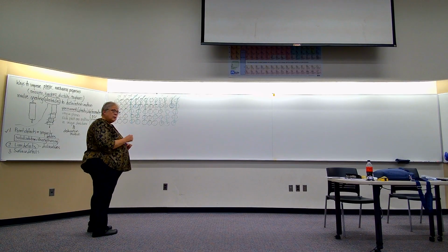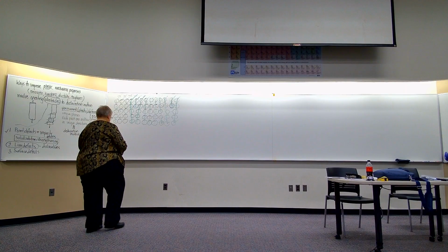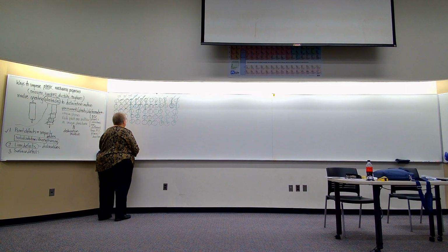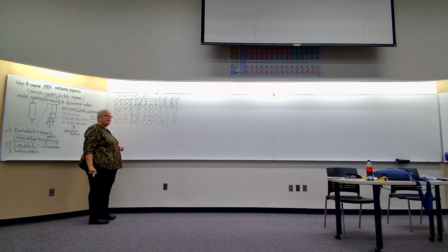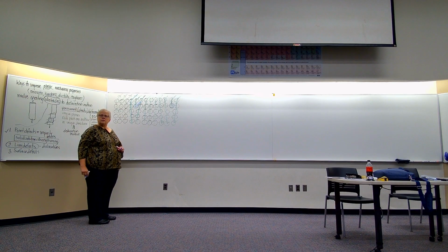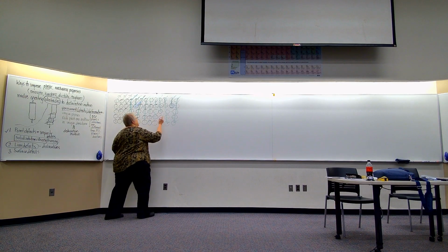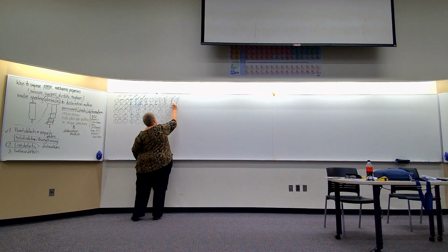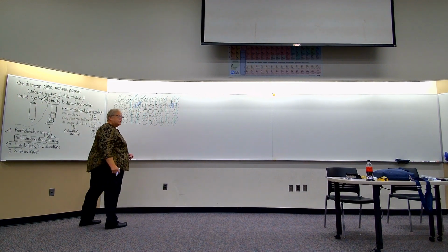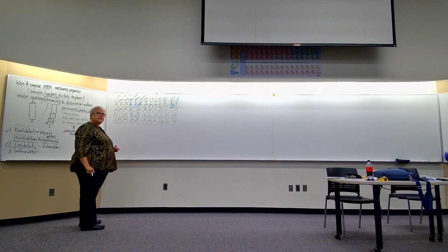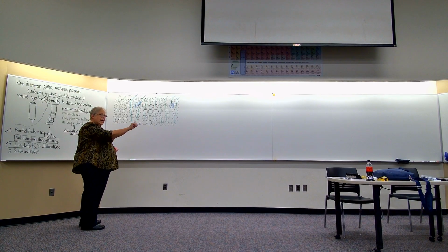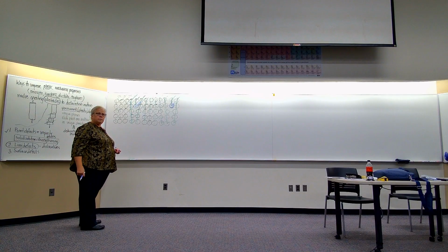Okay? So this atom here, and everyone behind it, that line of atoms, all of which are missing a bond, that is the dislocation. This line of atoms and all that are behind it is a line defect, a 2D defect, a row of atoms all missing a bond underneath.